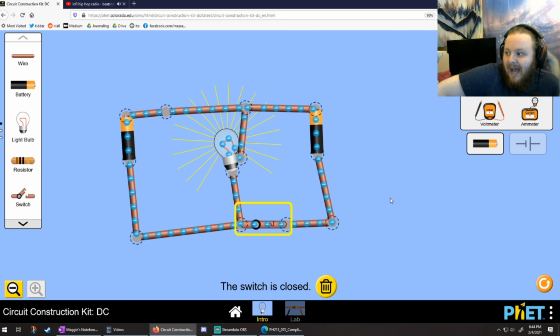current. And this is, in fact, how you make the power draw out of a battery smaller. If you've ever seen batteries in series inside of a remote or something, the more batteries you put in series, the lower the current draw out of each one individually becomes, such that you don't overload any of the individual batteries, while you're still supplying 1V worth of voltage. But you're reducing the current load on each battery, therefore reducing the wattage that each battery is outputting to make them last longer. This doubles the lifetime of the battery, and the more batteries you put in sequence, the longer their lifetime is.